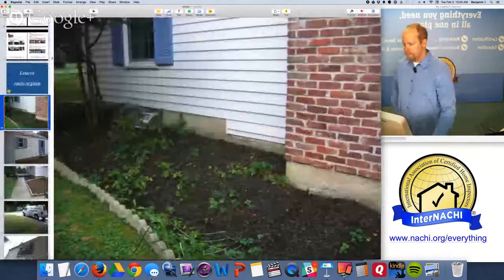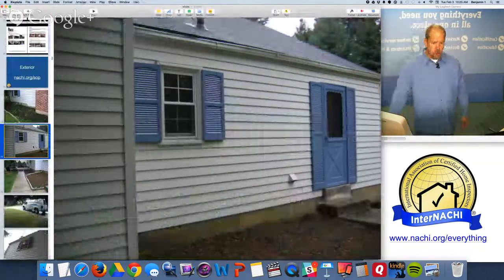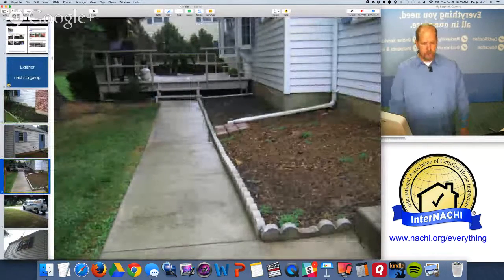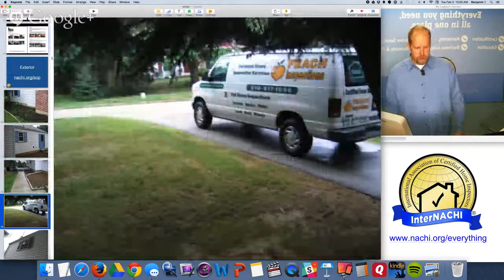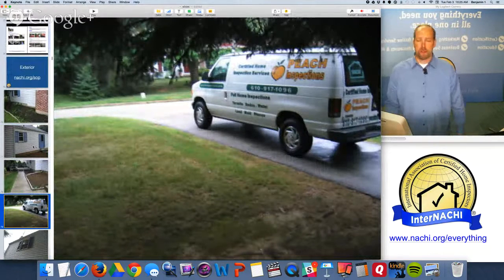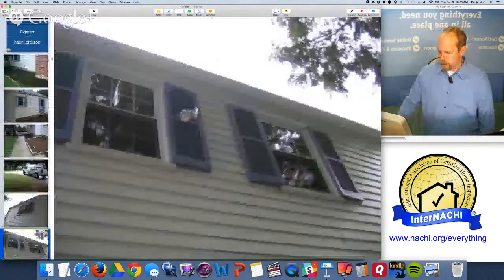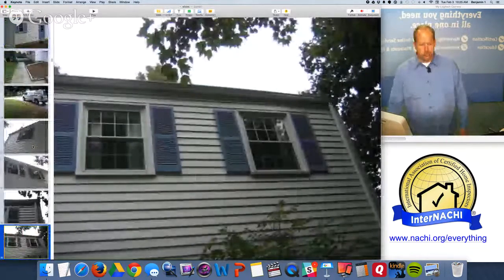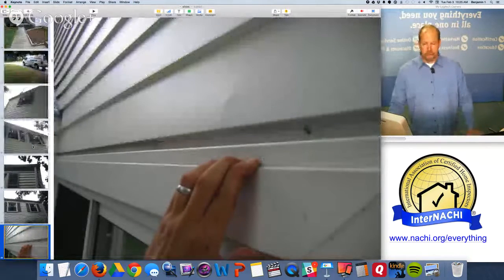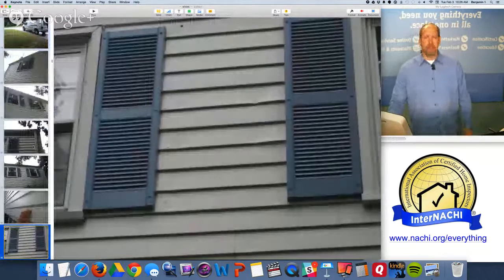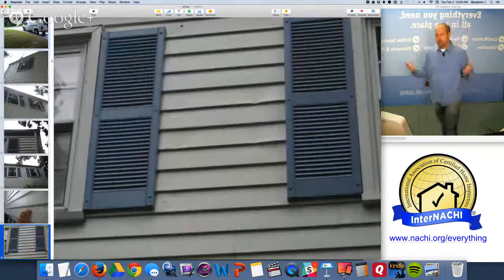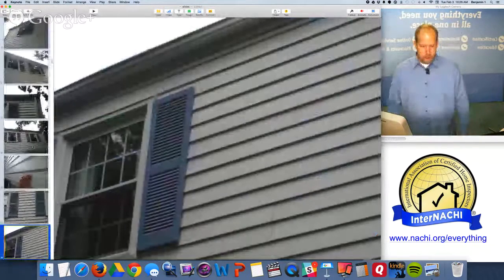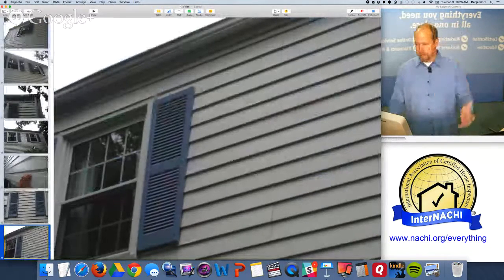The exterior wall covering materials, siding materials, there's the walkways, there's the driveway, there's the money shot. Take a picture of your inspection vehicle all the time, put it in your report. You're not required to inspect the second floor windows. You can't reach them from the ground, but you can use your zoom and your camera to take pictures. I take pictures of everything that I can possibly take a picture of. I take hundreds of pictures, and digital images are free. So take a lot of pictures, take a lot of video. I share them with my client on a USB.